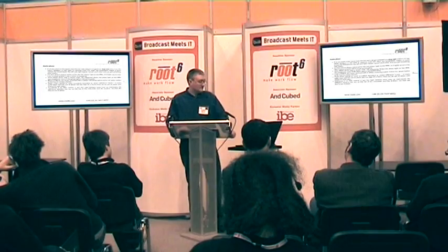Your PPM will have a little phase light, a small red LED, which when it detects that phase difference, when it detects that reversal in one channel of the audio, will light up a red light to warn you that you have a phase problem between your left and right channels, and you should investigate that further. It's easy to rectify, but can be disastrous if it makes it through to transmission.